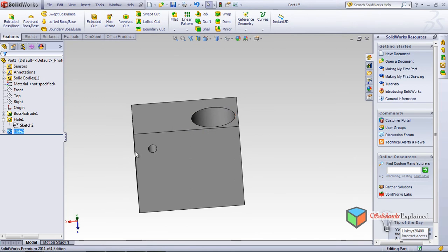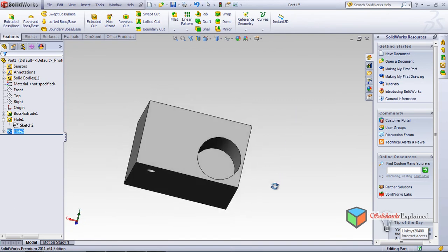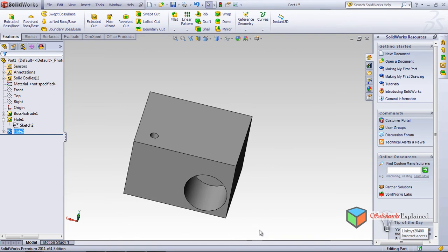Let's say this part was containing two holes, two extrudes, two cylinders, many things in a single part, and the tree becomes very long. In this case also you can scale the part. Now how to scale the complete part is a challenge. If it is a simple part, then you can directly go to the sketch and just scale the sketch bigger or smaller, and then come back.